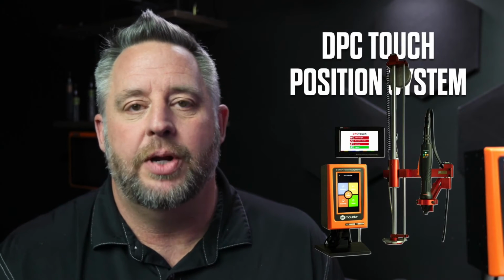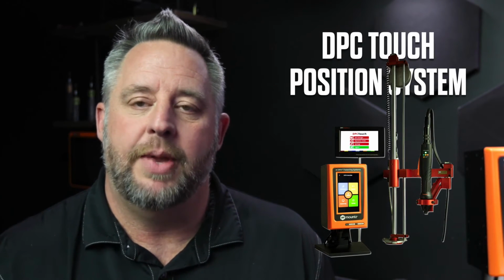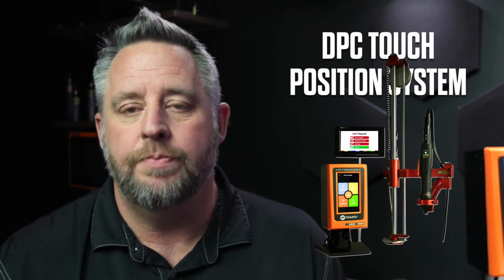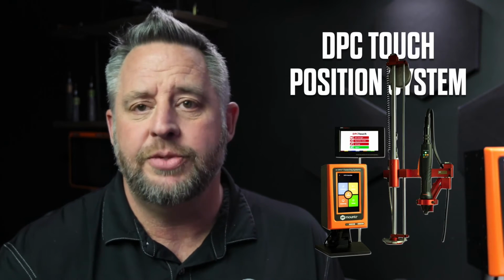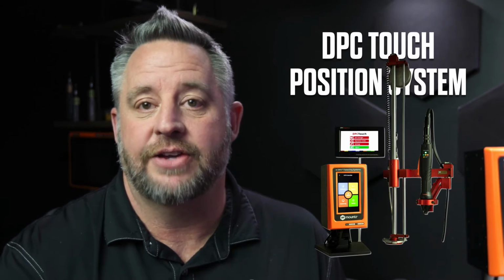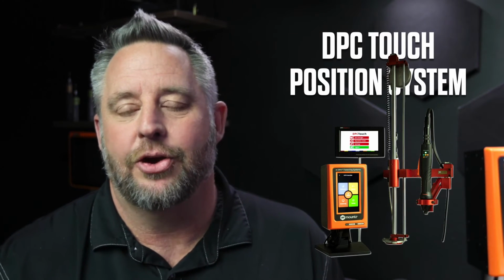So there is one other piece of equipment that could certainly help with this, and we do have other webinars on the use of our DPC Touch position control system. What this does is allow power to only be sent to the tool when the tool is in the correct location. So we can set up different fastening programs, and the tool is only going to work when it is on the right fastener. The operator can try to use the tool in any other spot, but there's not going to be any power to the tool unless they're in the correct location.